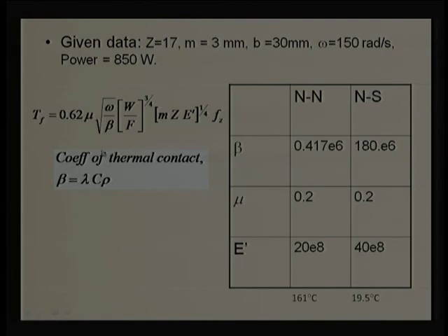And this is an important aspect. Whenever we choose a gear material, we need to think about good thermal conductivity, because at the contact point there is a possibility of high temperature, and there is metal to metal contact. In this whole example, we took a coefficient of friction equal to 0.2, but if we provide some sort of lesser coefficient of friction, then it is going to affect the results. If I decrease this coefficient of friction, maybe 10 times, naturally this temperature is going to reduce 10 times. But in those situations, selecting nylon will not be having any use. It can be removed, or we can choose some alternative material.